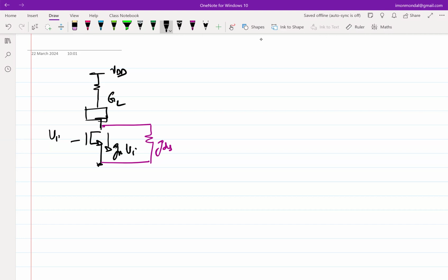And we saw that, I mean, a few lectures before that, we spent some time figuring out what type of sources give what type of impedances and so on. And in this case, looks like current controlled current source is the obvious choice. So then we replace this box with the current controlled current source that we know of. The only current controlled current source that we have extensively studied is the common gate topology, right?